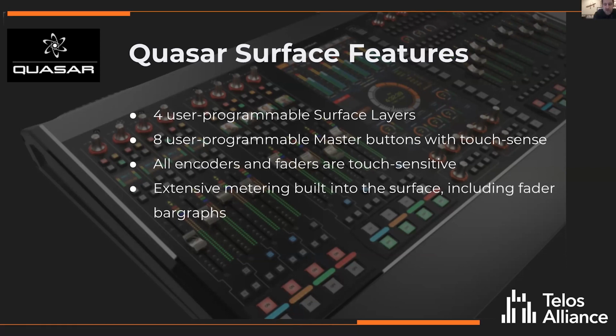Well, the touch-sensitive encoders and faders, for some of it, it's a very practical idea. So faders have to be touch-sensitive when they're motorized. That way, if you have an automation system that is trying to control those fader levels, the automation system will realize, or the Quasar will realize, when you actually have your finger on a fader, and you will override the automation system trying to change that fader, so you don't have grinding gears or problems or conflicts in control.